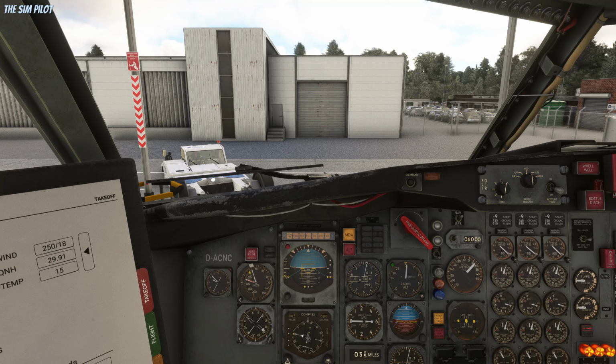If not, that's gonna also tell us that when we reach 3000 above ground, we will come back on the throttles and set our climb thrust for the rest of the climb. So that's another reason. So that's why I'm capturing my current altitude, as an additional aid to know when I reach 1500 and 3000 above ground level for the throttle management.